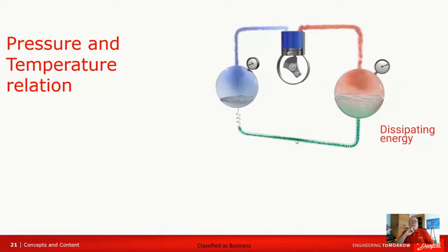Refrigerant boils at an atmospheric temperature. Is it different? Yeah, that depends on which refrigerant we're talking about. Some refrigerants might actually boil at atmospheric temperature. You can use, for instance, our fantastic app, the refrigerant slider, to find a refrigerant that actually boils at one bar absolute or 0 bar gauge. Try it out and you'll see it.